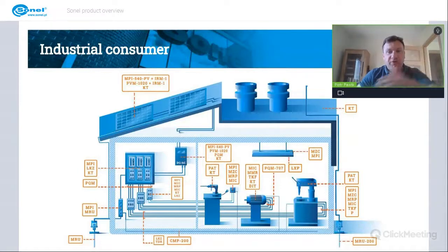So now we are coming from a transmission network, and the energy will get to our distribution board. So here is the main distribution board. And further on, we have some switchboards where we can find safety switches. So what can we test here? Again, we can test the short circuit loop. We can check the RCDs. We can check the insulation resistance.